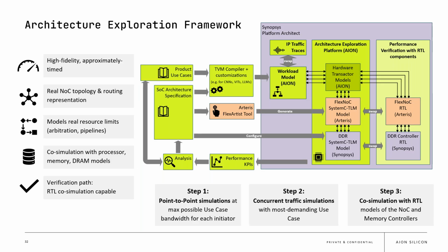You want to ensure that your platform can support the bandwidth and latency requirements for that. In this stage, you might need to modify your NoC topology slightly, but the bulk of the work should have already been done in step one. Step two is fine tuning.